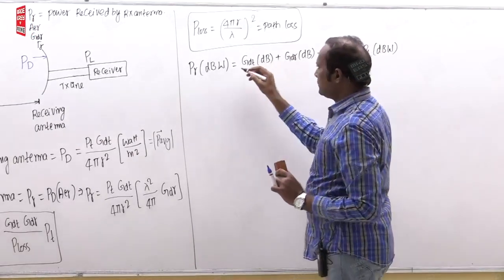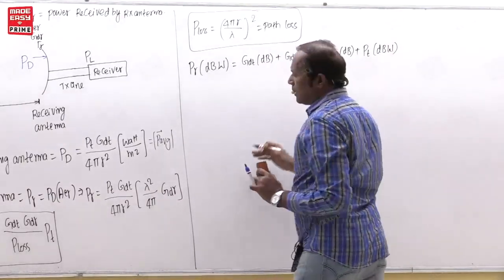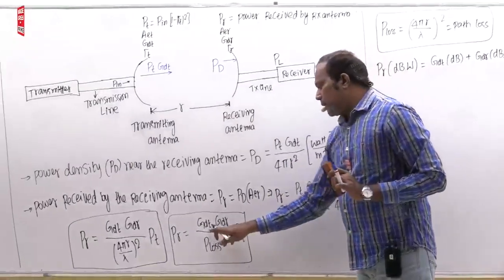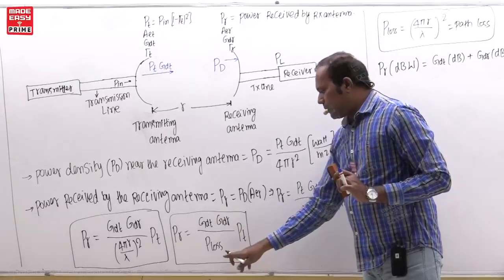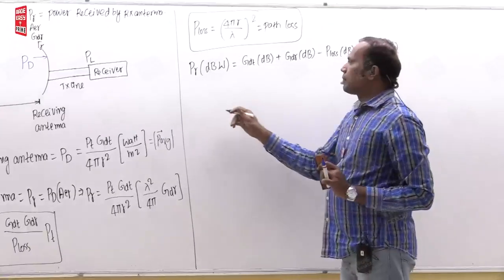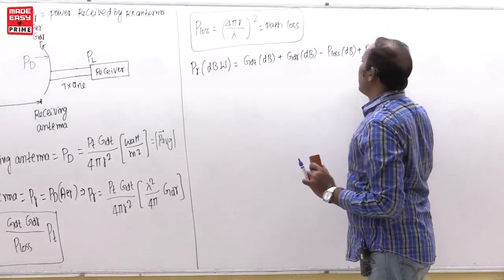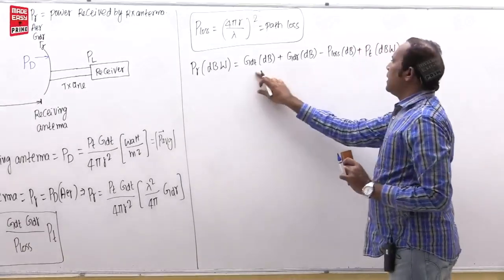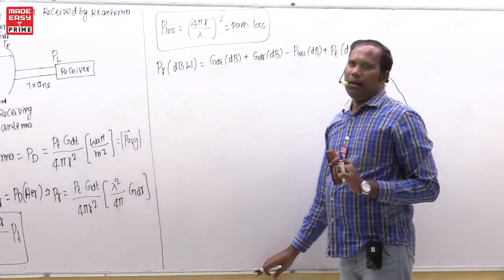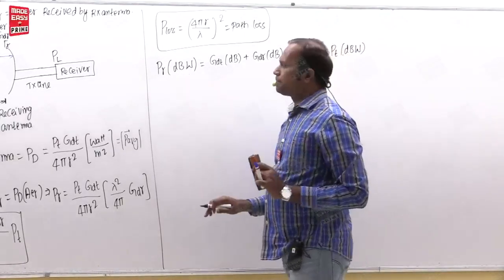If you remember this, that is more than enough, because in decibels numerator quantities are added and the denominator is subtracted. Here you have to understand one thing: if you represent transmitted power in dB watt, then received power is also in dB watt. If you represent in dBmW, milliwatt, this is also dBm. If you represent in dB microwatt, this is also dB microwatt.